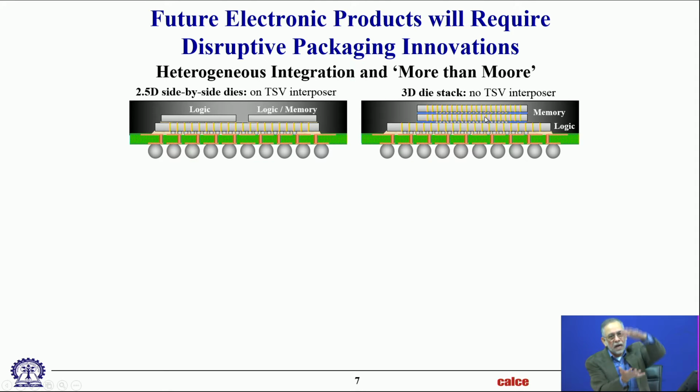They're all directly stacked die on die on die, and then they have to talk to each other through the thickness direction, which is why you need vias that go through the silicon. TSV, as many of you already know, is through silicon vias. Those are interconnections that are made in the thickness direction, so these multiple dies can talk to each other.